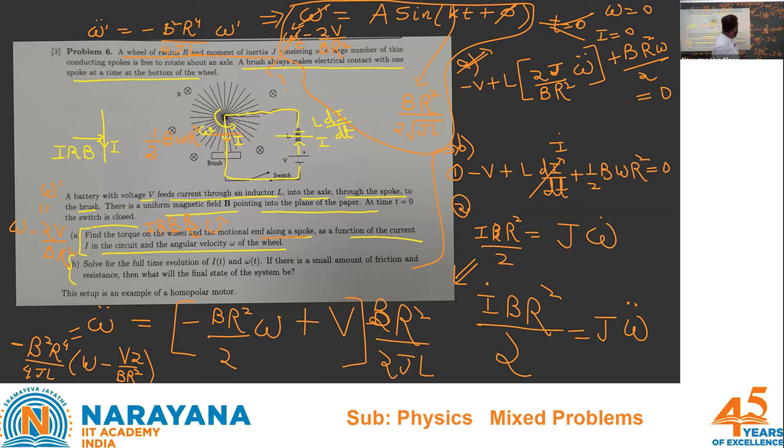Right? So I am not going through the calculations. You can spend 2-3 minutes more and try to go through the final calculations. I'll just dictate the final expression which comes up. Finally, omega as function of time comes out as 2v upon br square in bracket 1 minus cos kt, and that kt term is br square upon that term, and your current comes out as v upon kl sin kt. Current also comes.